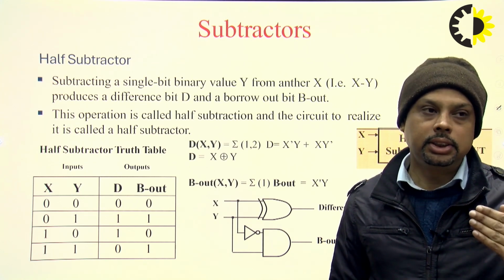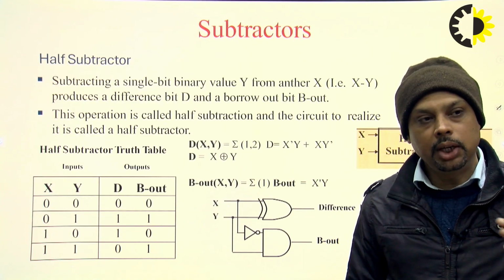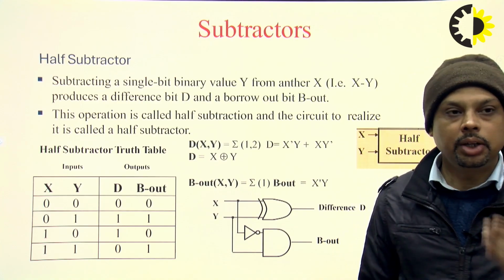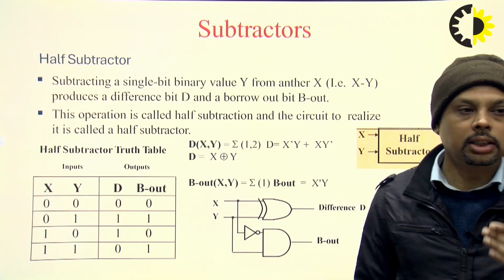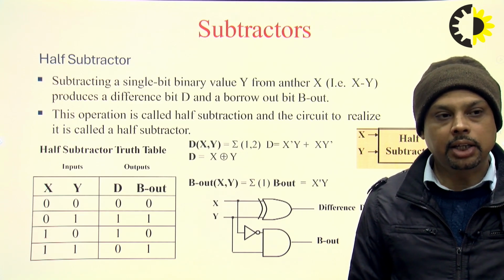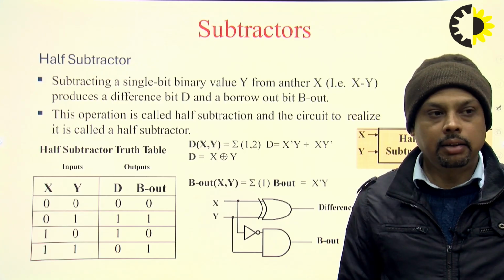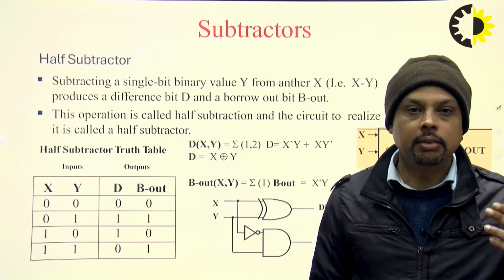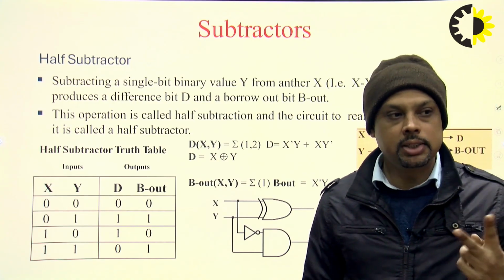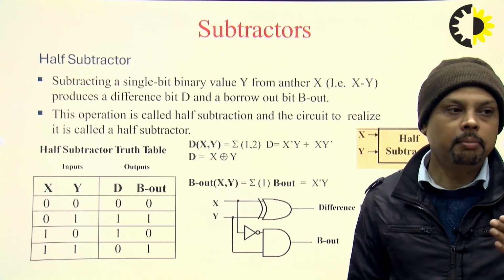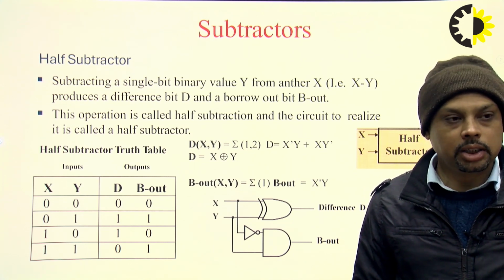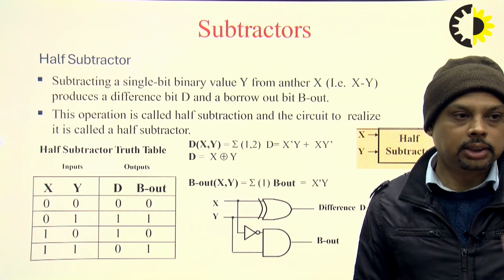First we decide the number of input variables and the corresponding output variables needed for a particular circuit design. In the case of our subtractor, we need at least 2 bits as input, so that 1 bit is subtracted from the other bit, and it produces a result that is either the difference, or a borrow that is needed in the subtraction process.